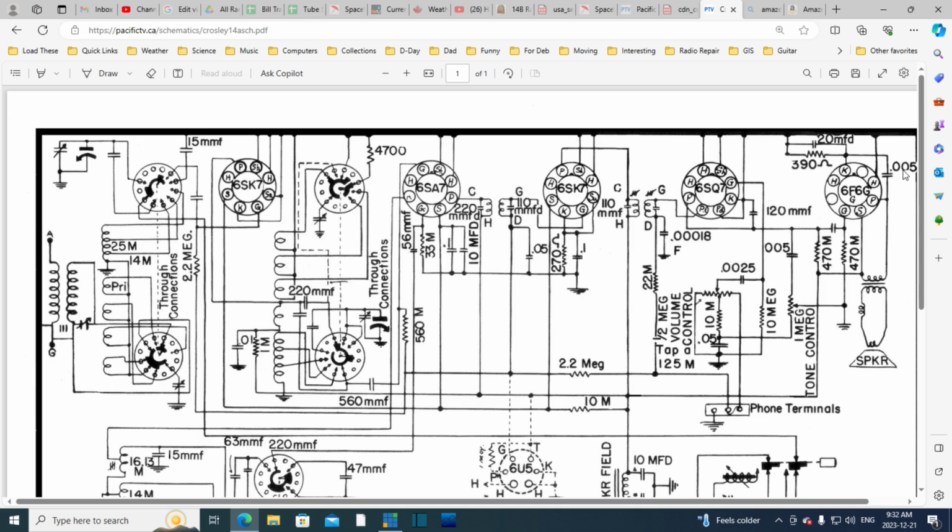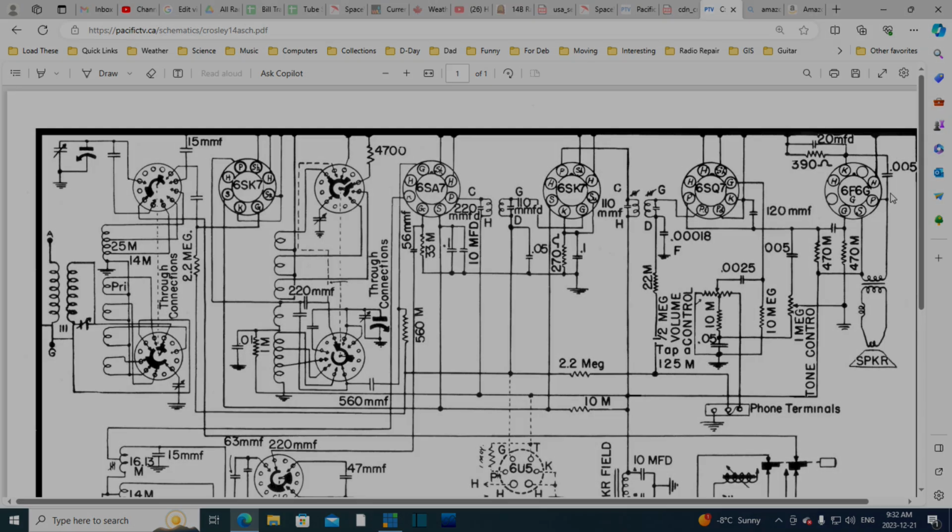So when I encounter these kinds of things, the first thing I think is, Jim, you're just making a mistake somewhere. You're doing something stupid. You're looking at the wrong tube. You've got the pin count backwards. You haven't seen a wire. If you look harder, you'll see it. There aren't two capacitors connected here. There's just the wire heading up to the speaker and this capacitor which goes to ground. I mean, there's just no option here for it to be anything other than what I think it is. So you know what that means? That means time to stop and have some coffee.